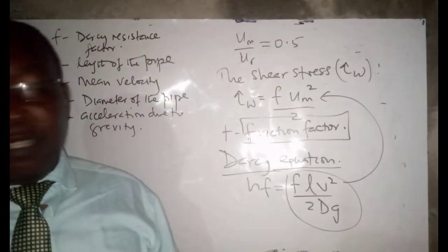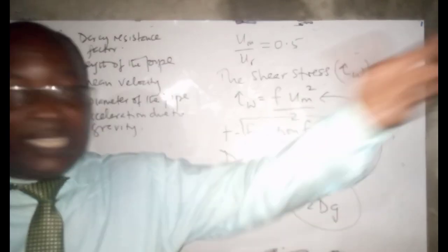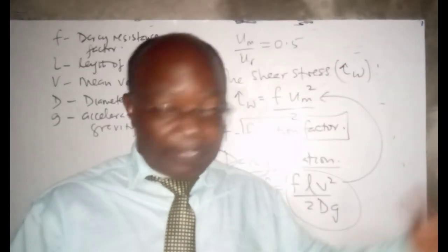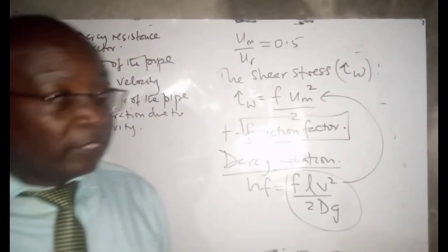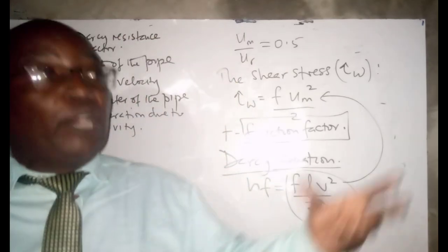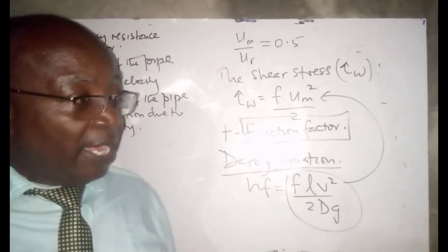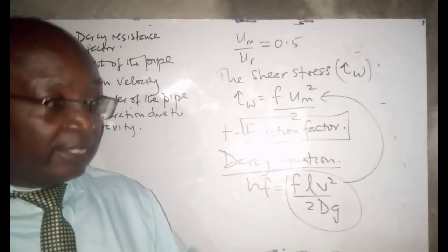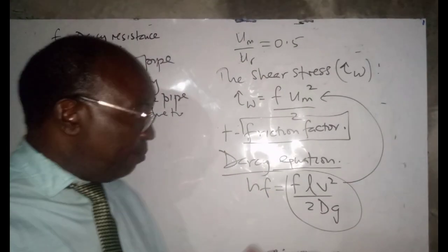And of course, it depends on, for example, the age of those pipes. Maybe there's a lot of silting on the wall, and so forth. But you expect that if it's just a clear pipe, then it should move on freely. But otherwise, if there are depositions on the walls, those regions can act like a turbulator of sorts, initiate the turbulence process. And in those areas, you find the Reynolds number is enhanced, greater than 2300. And so these are important things to know.